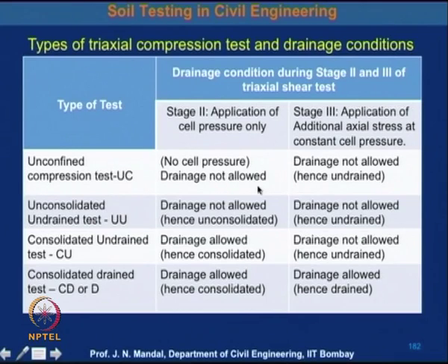In the third stage, the application of additional axial stress at constant cell pressure, drainage is not allowed, hence it is undrained.